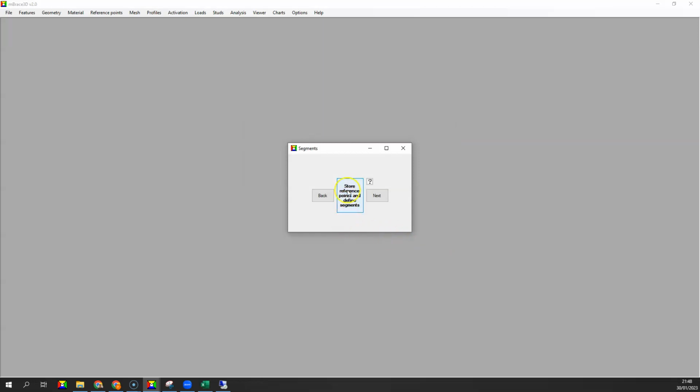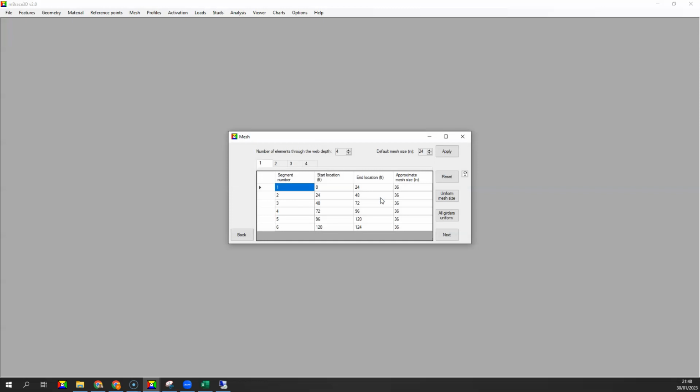I will not click on this button here as the model is already run, but again, as I keep saying in every tutorial, if this is the first time you come across this form, please click on it, and same if you modify any of the reference points. This is in order to have subroutines for the mesh properly define the right geometry for the bridge.